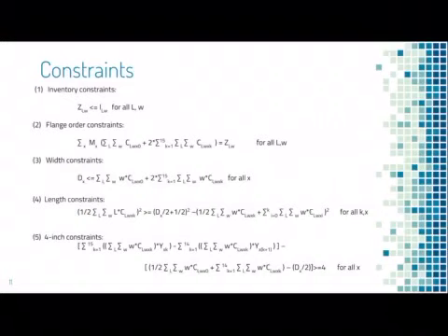Our third constraint is that the sum of board widths should match the flange diameter. The fourth one is, according to the Pythagorean theorem, the square of the required length of the board over 2 plus the square of the distance from center to the end of the last board should be greater than or equal to the square of the radius.